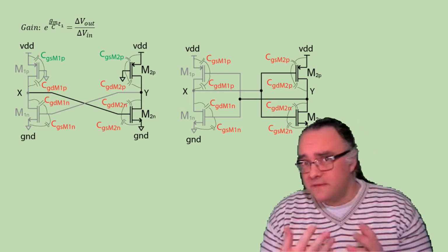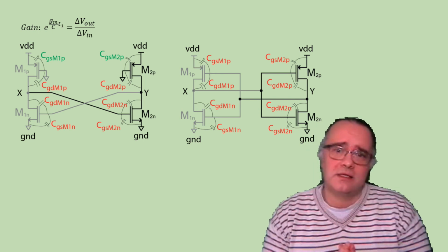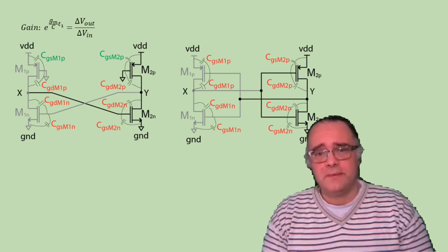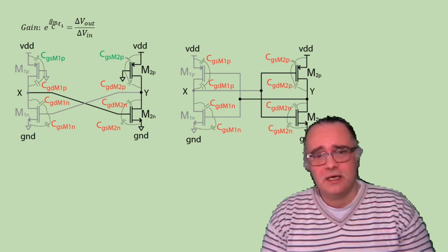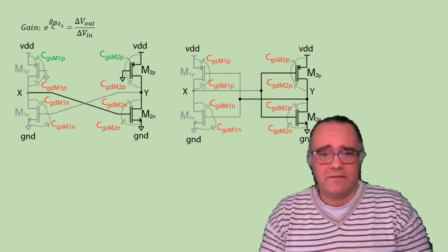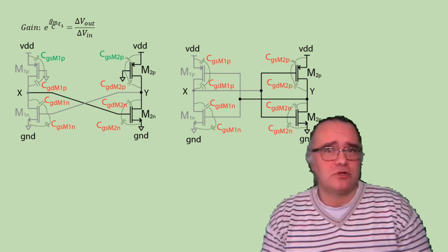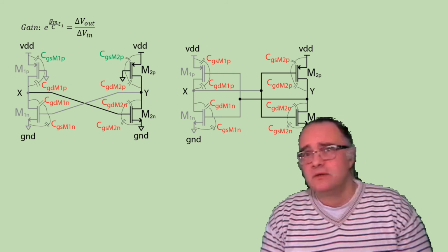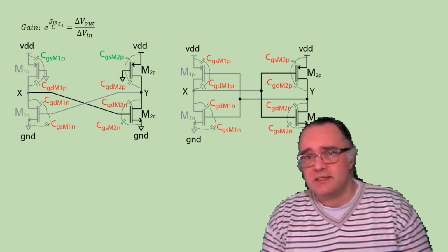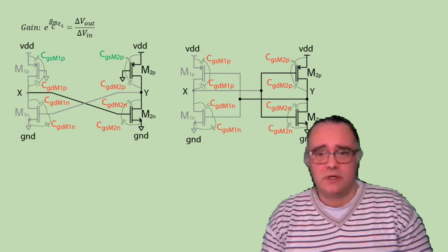There are different transistor-level implementations, realizations of the latch. Here I give two examples which are often seen in implementations. On the left side you have an inverter realized as a common source transistor with a PMOS load, and on the other side you have the inverter realized with NMOS and PMOS transistors.